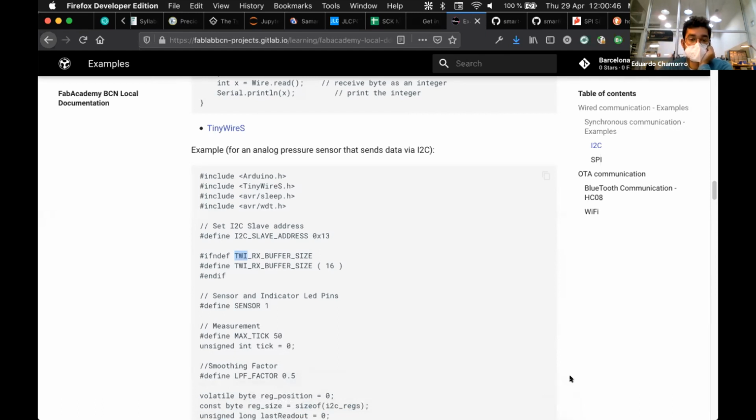So if you're looking for information in the datasheet or other libraries for ATtinies, it's different for the new series that you were trying yesterday with the 1614, but for the old ones, you have to use TWI, which is two-wire interface. So if you don't find I2C on ATtiny44, look for TWI on ATtiny44, because that's how people normally implement it.